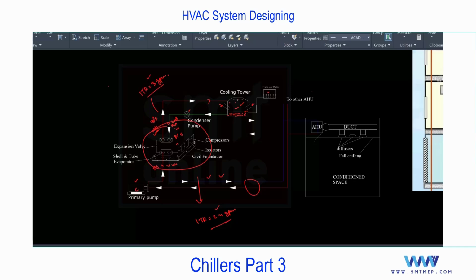Again, apart from this, for the life of the system, if you use only water, like you see, normally in our car radiators we are using coolant, not just water. We are using coolant to increase the life of that heat exchanger. But the coolant is not used to extract the heat. The water is responsible to extract the heat. If you use pure coolant in the car, that will not help to reduce the heat of the radiator. Water is a must. With the water, partly coolant is required, so that the coolant will help to not damage that system, to reduce the oxidation.